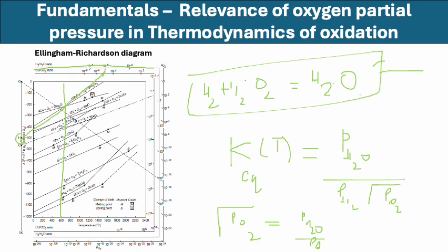If I intersect that line here, so let's erase this particular line here. Except when we have very low hydrogen to water ratio or very high water to hydrogen ratio, we cannot form oxide for copper. If you use this green curve, same logic, but you need to draw a line from the point H on the left side of the axis.